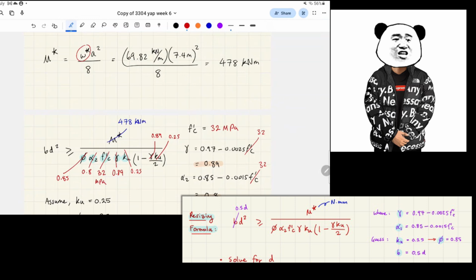Okay. The other ones are actually unitless. But MPa is basically newtons per millimeter squared, which is correct in this case. Yeah, it's correct. But we want to change the top so that it matches the units. So we can times this by 10 to the 6. So this times 10 to the 6 results in newton millimeters, just so we're working in the correct set of units.